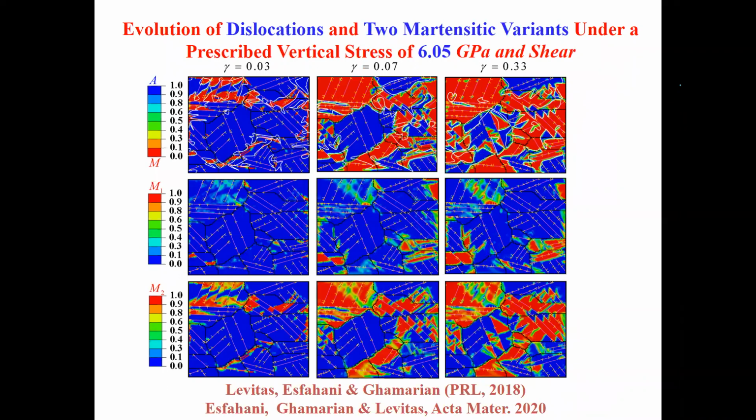Okay, now it's microscale. One of the drawbacks of the nanoscale phase field approach is that it resolves actual phase interfaces. And this is like 1 nanometer, and we need 4, 5 finite elements to resolve this, to obtain a mesh-independent solution. That means, by definition, we cannot treat large samples. That is why we developed a completely different microscale, scale-free phase field approach.